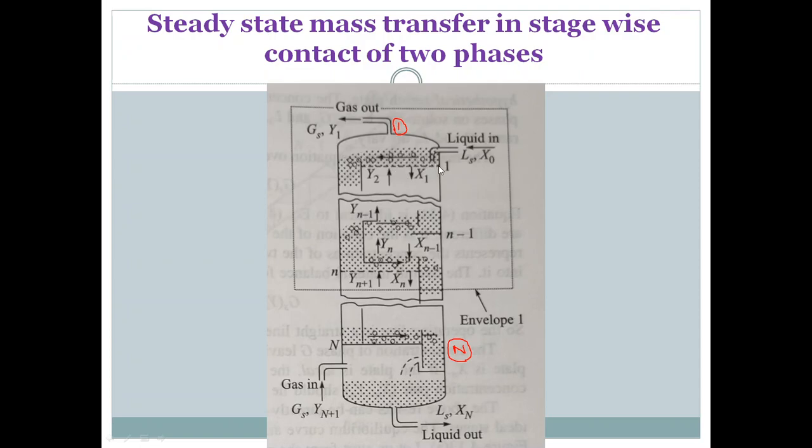So take the first stage, stage 1, the first unit. The hollow cylinder is there, here I make a circular plate, and I cut one side, let's say 10%. Where I cut this, I will keep a 2-inch partition, that is called a weir, so that here the liquid will hold up. So when liquid comes from the top, it will hold up, and when the level is higher than this, then it will come down.